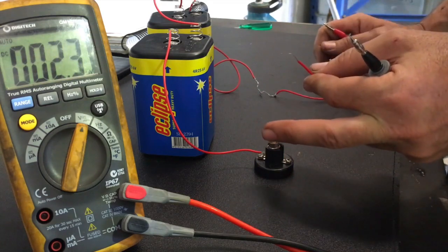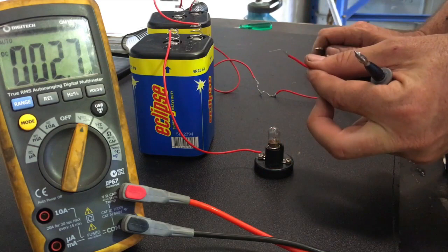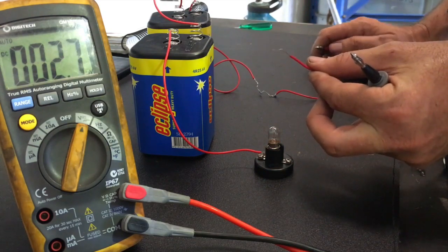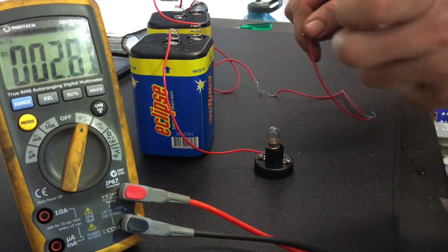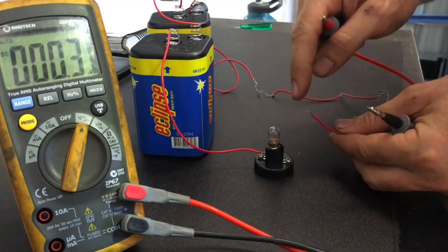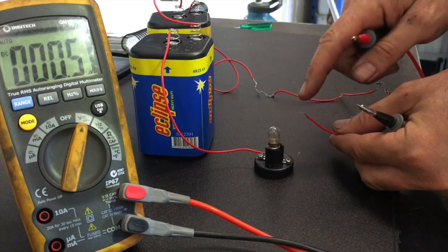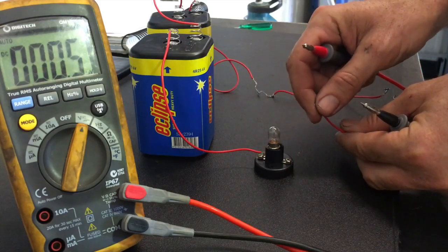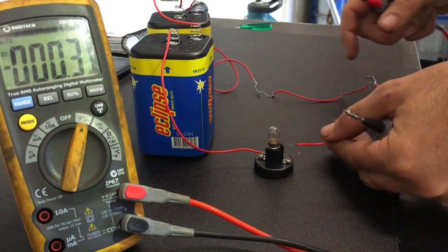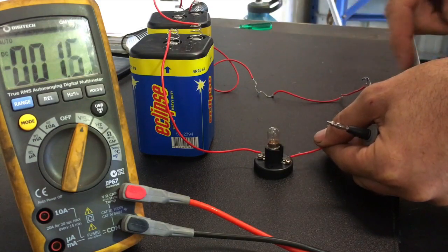Yes, 12.8 volts is dropping across the entire circuit, that is true, but it doesn't mean it's all left to come here. So don't get this false sense of security that when you come to here, you are actually getting 12.8 volts to this point, even though that's where you're measuring it. So that's something to really wrap your head around when it comes to voltage drops, is they have to be measured in parallel, and you can measure it across different devices like we did earlier.